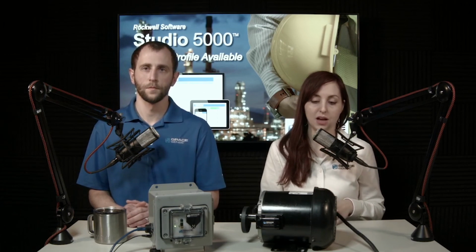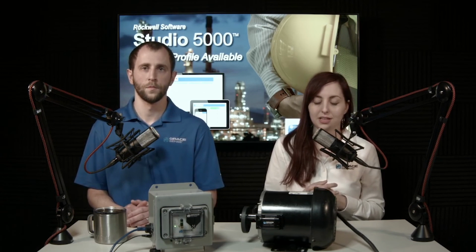All right. What extra information can you receive on the VBT2 versus the VBT1? Good question. The difference between the two is the VBT2 has a higher end accelerometer and a higher bandwidth. The VBT1 can go up to 800 hertz, but the VBT2 has X and Y axis to 4600 hertz and Z axis to 22,000 hertz. I would suggest using the VBT2 if you're targeting one of the higher frequency bands, to get better accuracy on those.